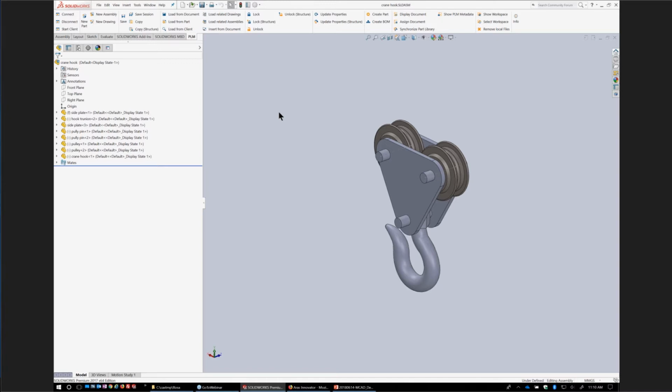This is important to mention because there are companies whose process involves creating or requesting a part number beforehand, before the actual engineering work, and then they come back and link it to the item in CAD. With that said, in our case, we're going to automatically create the part numbers and the part item directly from CAD.